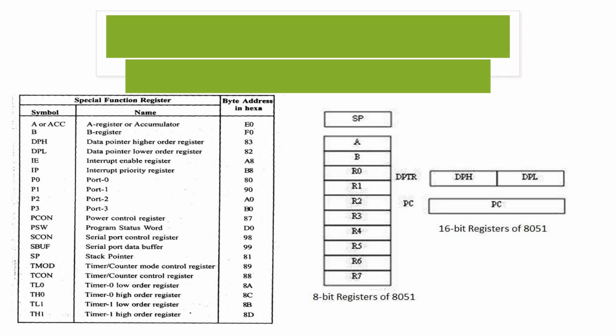Yes, and also you have A and B, that is nothing but accumulator and B register. So here accumulator is nothing but an 8-bit register that is used for primary operations within the CPU. And B register is also an 8-bit register used for general purpose data storage. So these are the two registers which have been used. So that is why you call them general purpose registers.